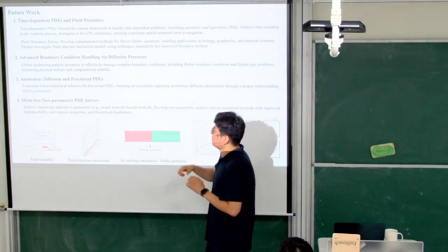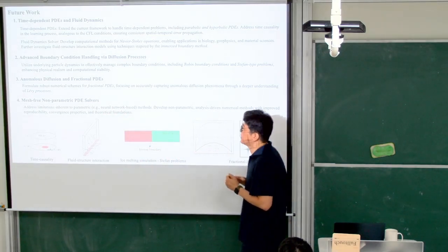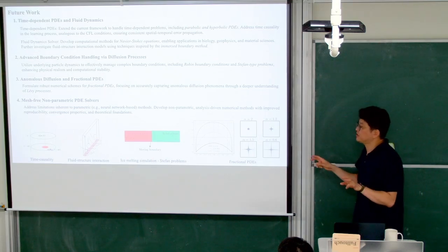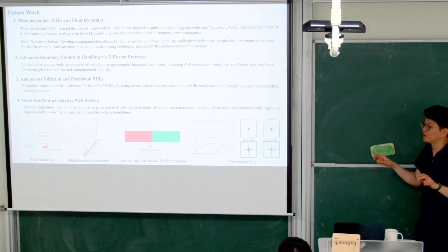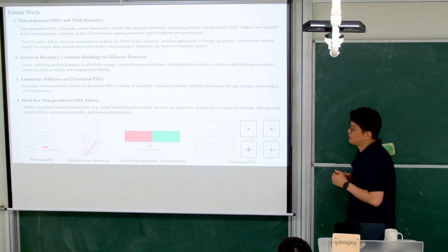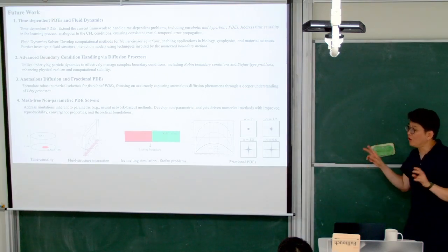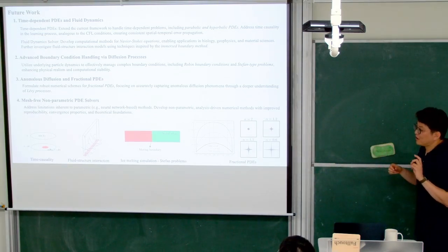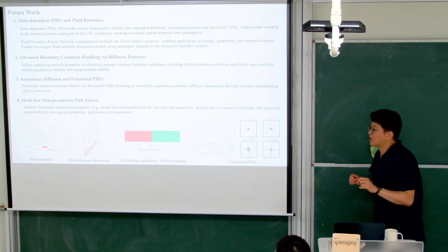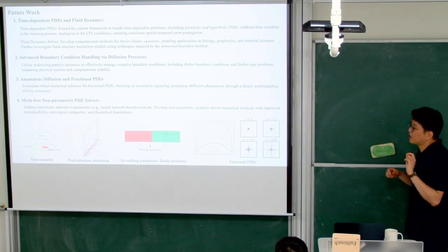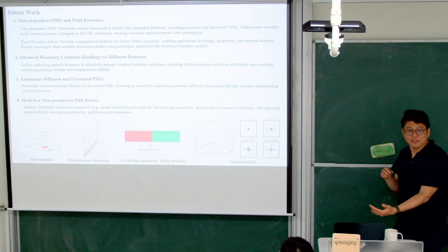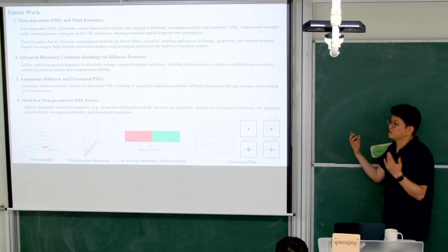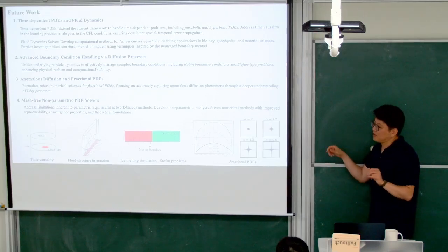And finally, this is one of the ultimate goals of this PDE solver. The advantage of the neural network approach is that it is mesh free. You do not require generating a mesh and it is easy to implement. This is one of the big advantages of the neural network. But the disadvantage is that it's very hard to reproduce, because it depends on optimization and on the random state, and convergence is not guaranteed.